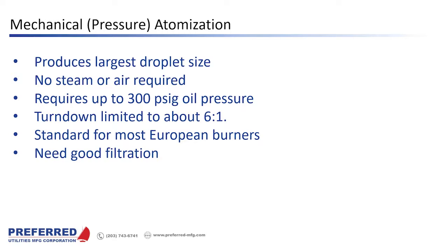And like I said, it's standard for most European burners, and to take most of that 300 PSI across the oil tip requires very small orifices, and those orifices are prone to plugging. So you need good filtration at the burner. And we can help you with that. We supply filters as well as strainers that can be installed just upstream of these.